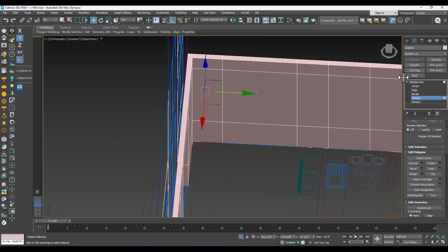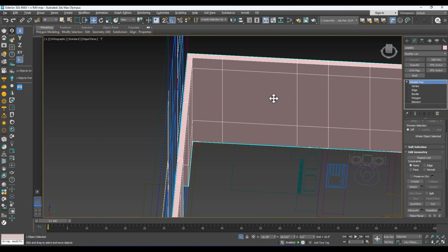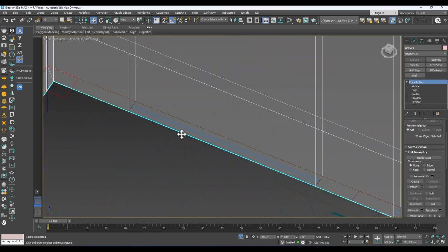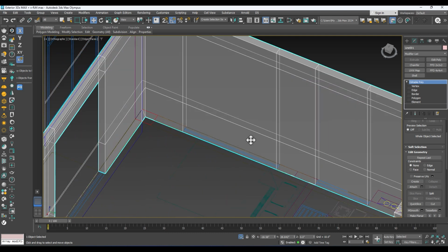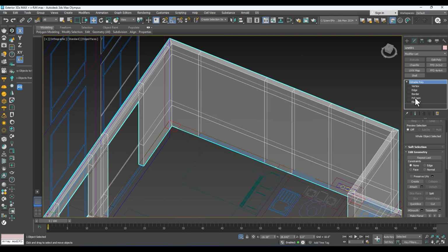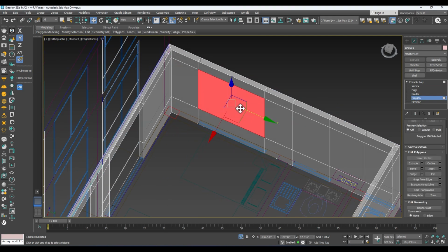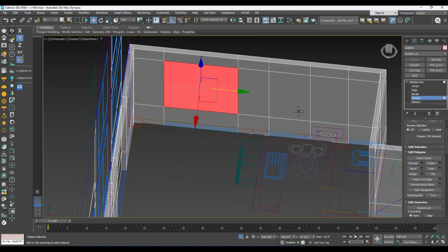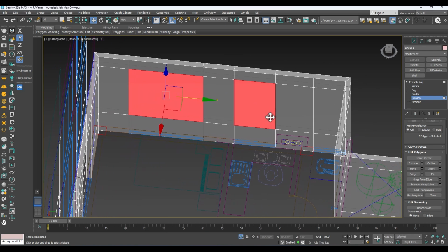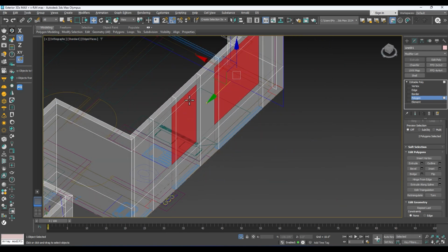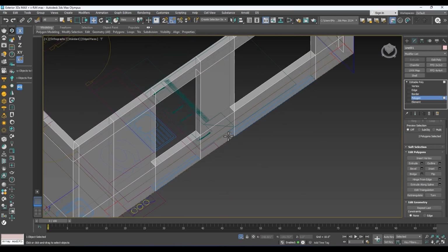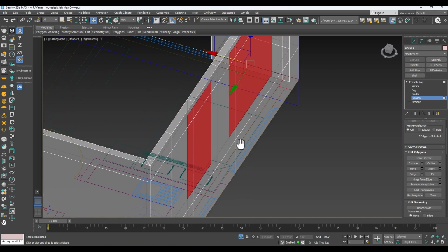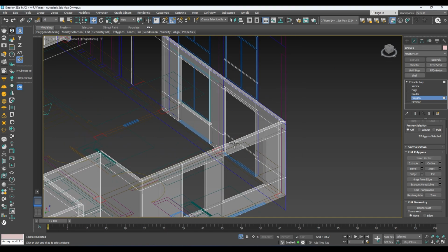So press Alt X to get transparent mode, so that you can see through to your windows reference and window drawing from your CAD layout. Then select the polygon, then select, then again here select, then punch. Then 1 2 3 boom.